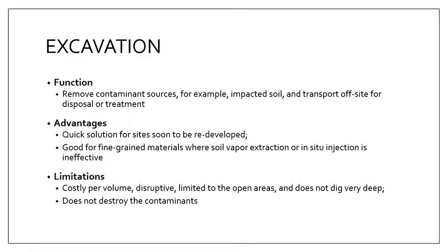And it is a good alternative when you have no other choices, and especially if your site is a fine-grained material like silt and clay, where other methods such as soil vapor extraction are not so effective. The limitation of this method is that, of course, it's expensive per volume.